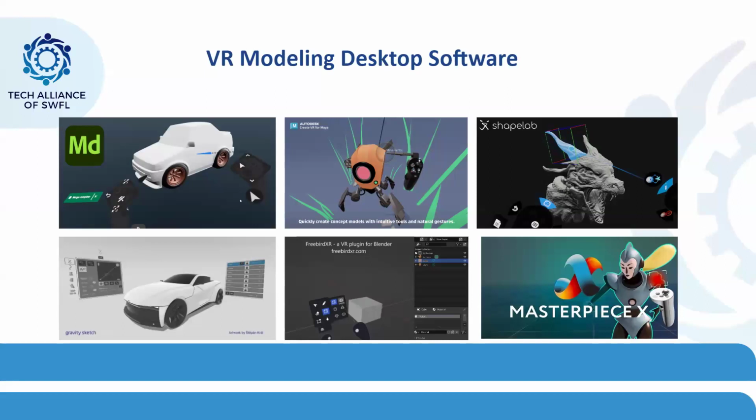But another option is the Autodesk suite of tools. Autodesk has Maya, and Maya has a plugin called Create VR, which allows you to create content using VR. I mean, it's in the name. The idea is that if you already work with Maya, you can bring your model into Maya, and in the viewport with this plugin enabled, you can just enable the VR mode, and you can switch back and forth between VR mode and your traditional desktop modeling software, which would be Maya in this case.